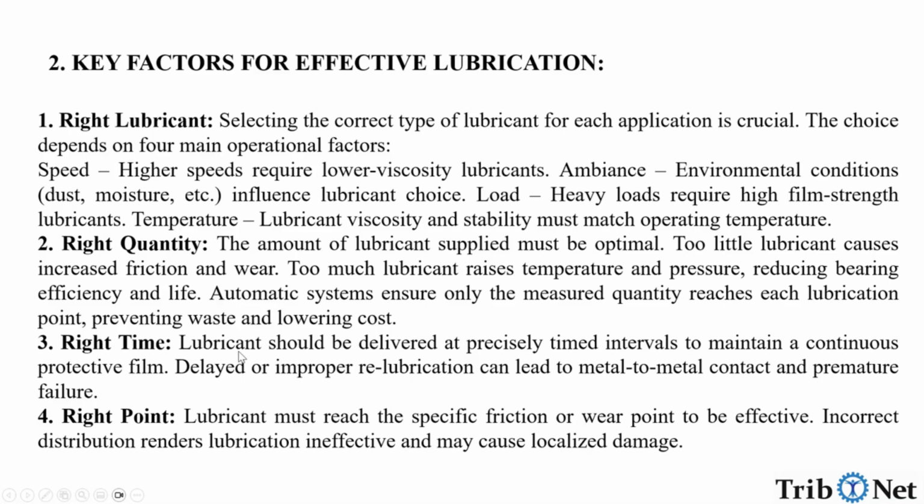The right time. Lubricant should be delivered at precisely timed intervals to maintain a continuous protective film. Delayed and/or improper relubrication can lead to metal-to-metal contact and premature failure. Right point. Lubricant must reach the specific friction or wear point to be effective. Incorrect distribution renders the lubrication ineffective and may cause localized damage.